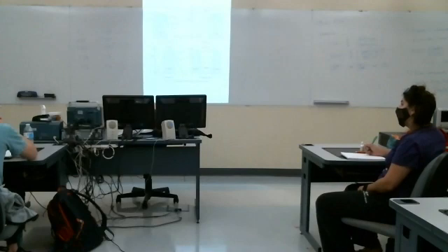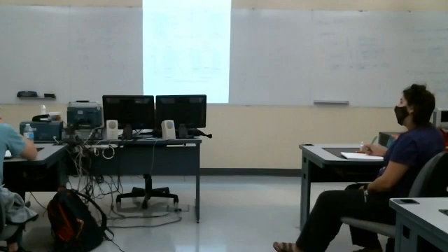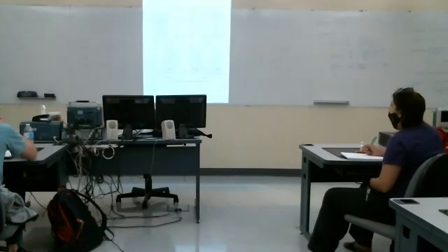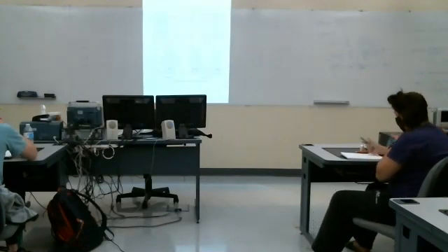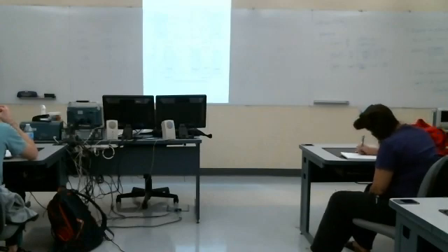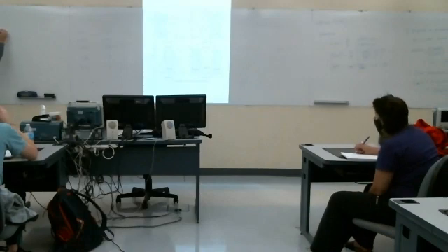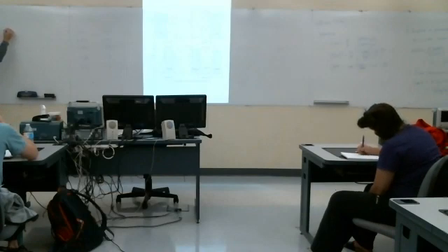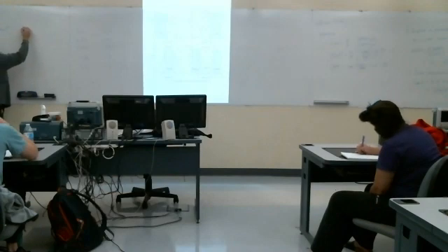So we're going to ignore the 1. So for omega greater than omega c, 20 log of 1 plus omega over omega c squared, to the 1/2, I'm going to say that that's approximately 20 log of this term squared, then the square root of that.